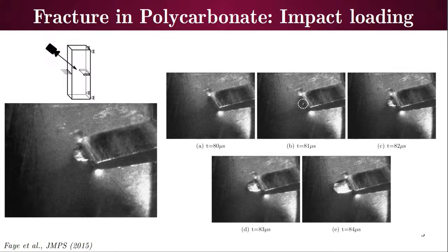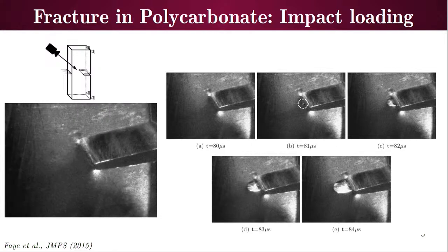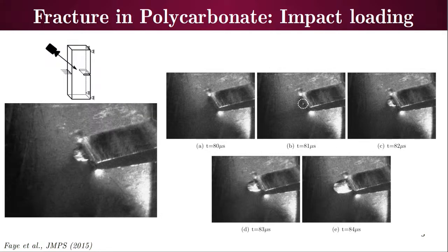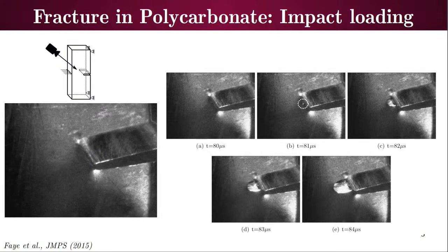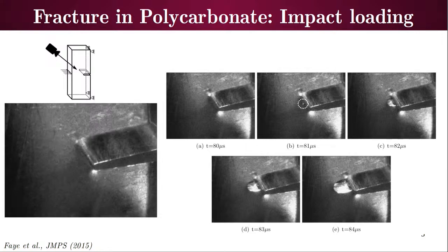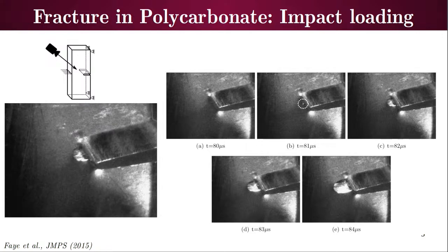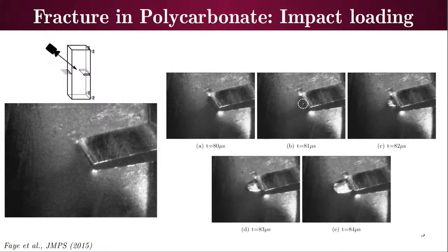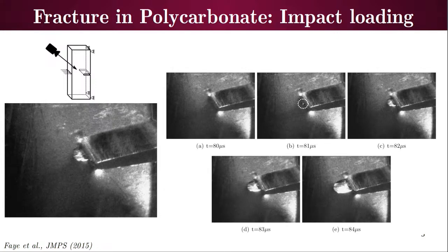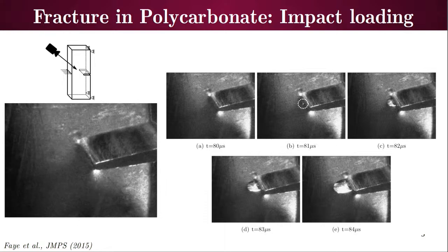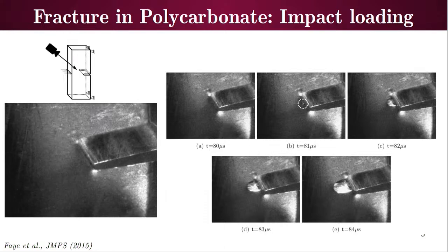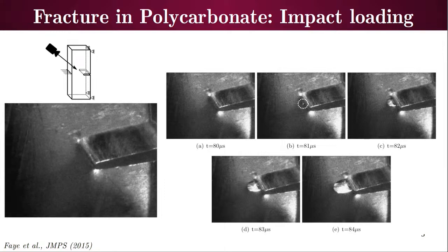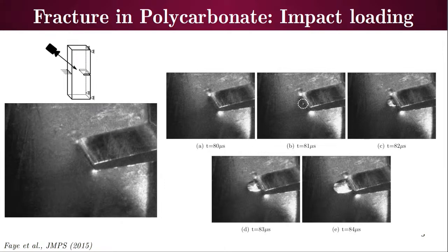Again the same 3-point bend configuration, the only thing is that it is under impact loading. Initially there is no defect, however you can see a small defect appearing in front of the crack, and then this defect spreads and connects with the main crack and the fracture happens. So the phenomenon remains more or less the same, the only thing is that in the initial static case the defect has a lot of time to accumulate, whereas in dynamic loading it does not grow bigger, it very soon joins with the main crack and failure happens. Okay.